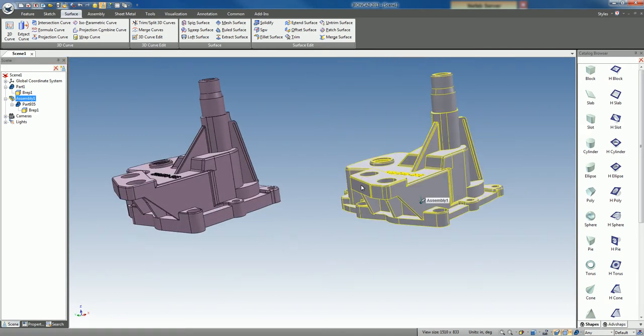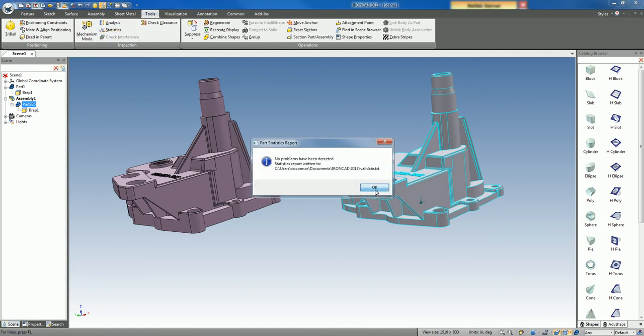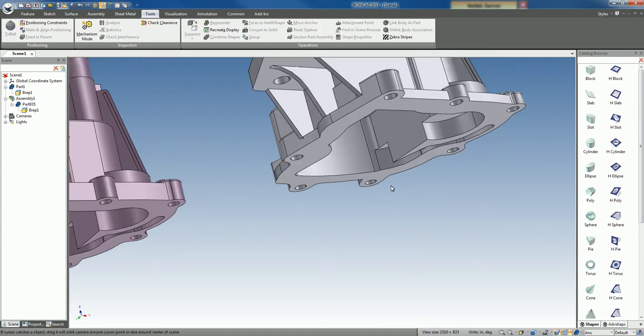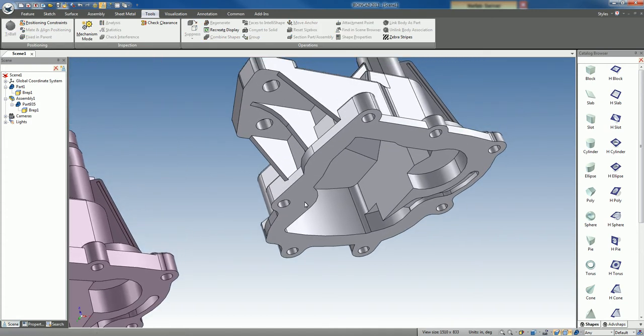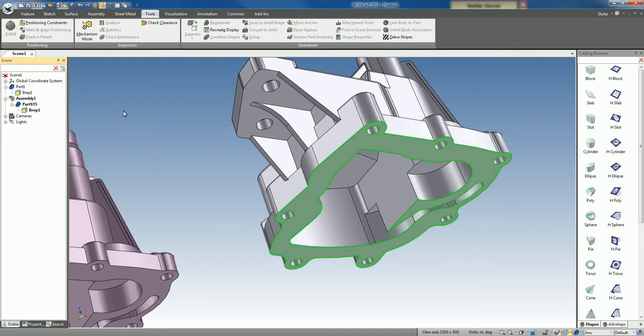If we run the statistics on this, same as we did for the Parasolid, in this case this one doesn't have any issues with self-intersecting. It's just a bit of a difference in how ACIS and Parasolid handle those self-intersections. Still, you can go down to these faces again, turn on our triball to do a direct modification, make a modification to it, apply that, and we can still do the direct modification on that as well.